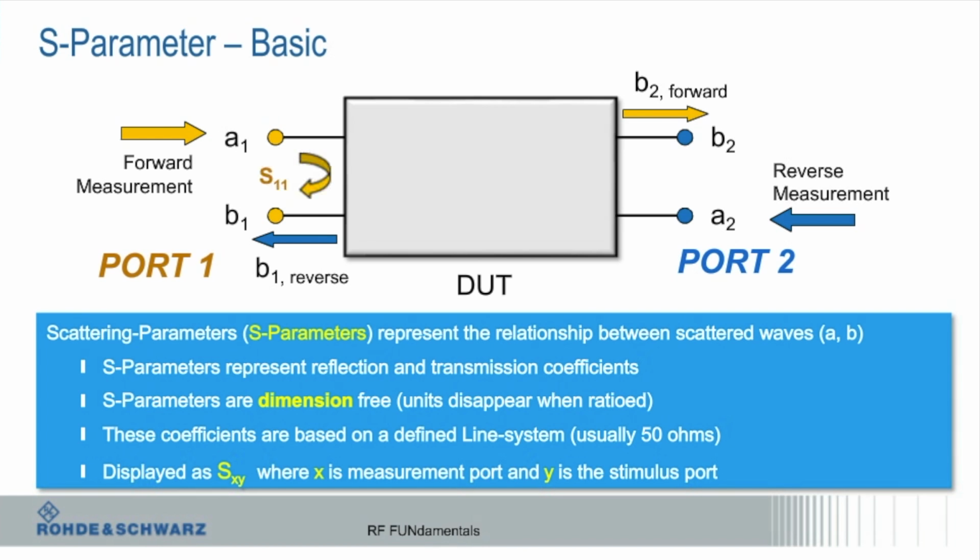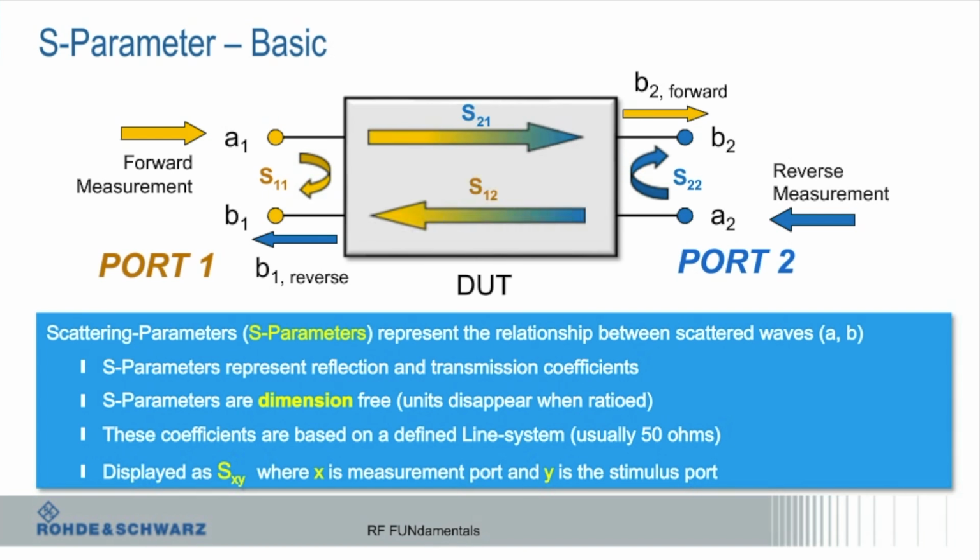Okay, so that's S11. I send out a signal, and it comes back. And I mentioned these before, S22, S21, S12. Those are the basic ones. And realize this is 2 ports, and this generates a 2x2 S parameter matrix. But obviously, I can have a 4-port. Guys who do differential measurements would have, instead of 1 in, 1 out, 2 in, 2 out. That gives you a 4x4 matrix. And we make one that's 24 ports, so that's even bigger.